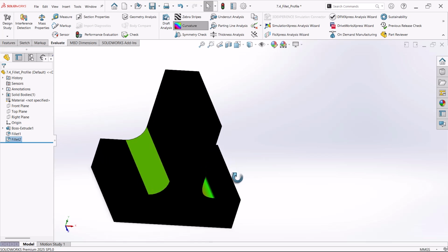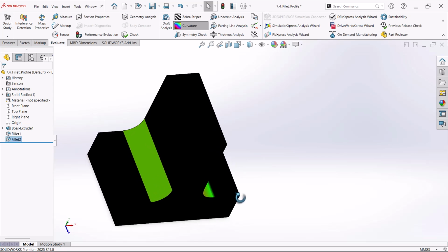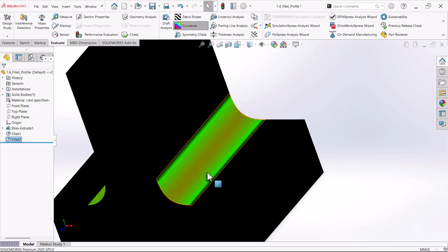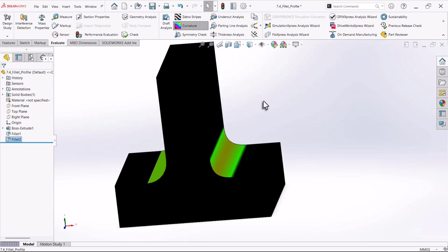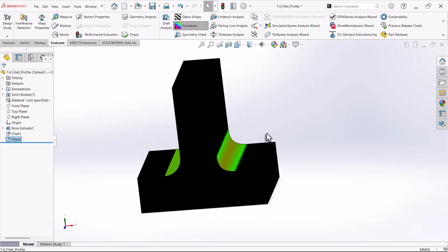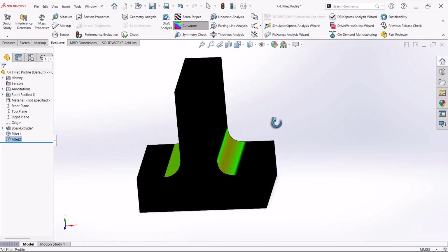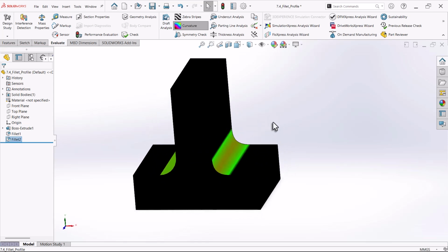Look at the left side, it is symmetric circular. There is no orange strip. Here, if you closely see, the curvature is basically changing from 6.4 to 8 and then 5 and 8. It tries to maintain the curvature with the surrounding faces. So if you require such a fillet, especially for creating the ergonomic shape on the handle side, edges side, or you can say on plastic components, there you can use such profile variations.